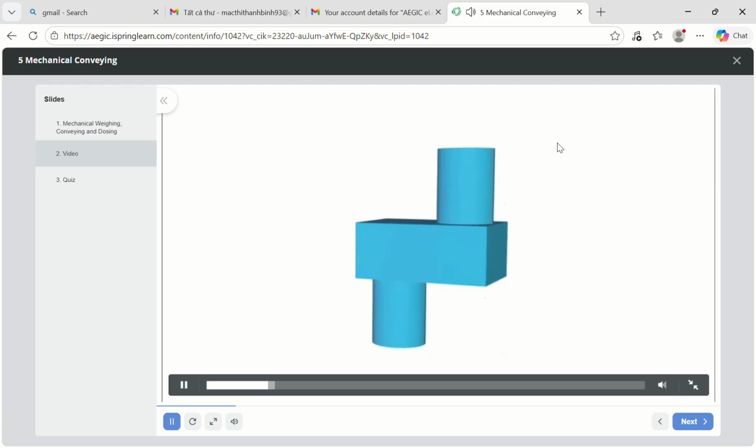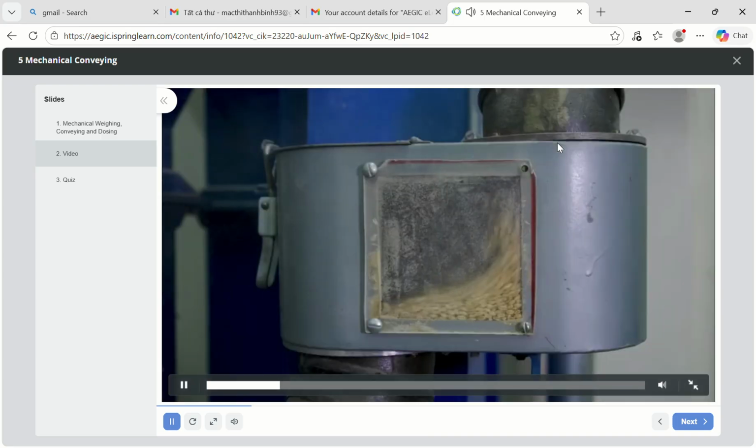Sometimes spill boxes are used to deliberately slow the stock. Fast-flowing wheat from above hits against the wheat in the spill box and exits with less energy. The spill box prevents the abrasive wheat wearing equipment or entering a machine too quickly.